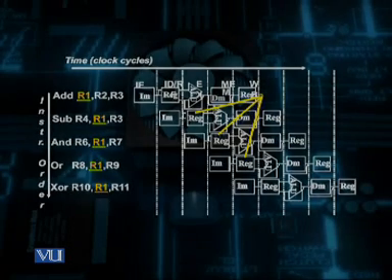This shows the data dependency of the 2nd, 3rd, and 4th instructions on the results of the first instruction. So this means that the 2nd, 3rd, and 4th instructions will not get the correct data till the end of the 3rd, 4th, and 5th clock cycles.